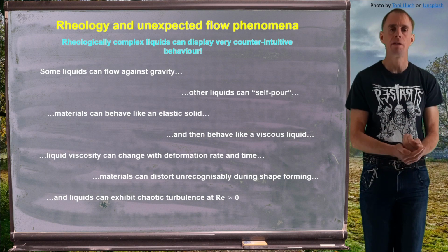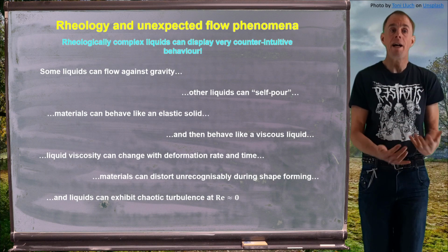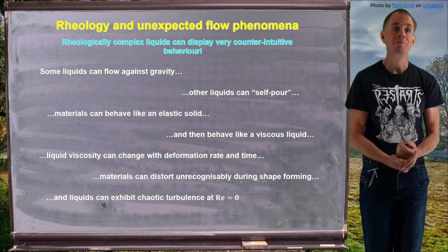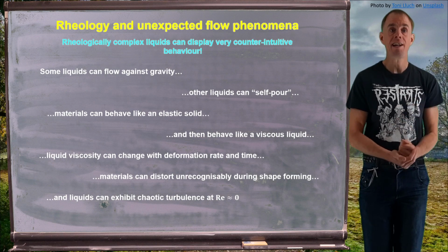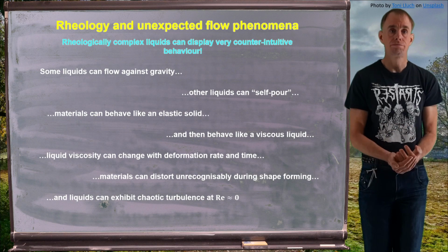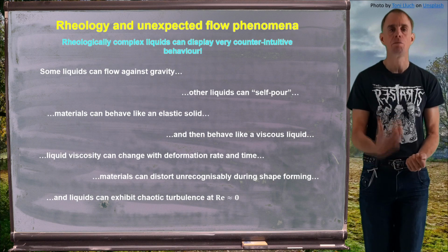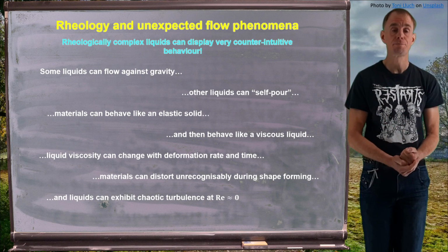Silly putty, for example. If you get silly putty and roll it up in a ball and throw that ball at a wall, it'll behave like a rubber ball. However, if you get that silly putty and leave it on a desk and come back an hour later, it will have formed a pool. And so you've got elastic behaviour at high deformation rate and viscous behaviour at low deformation rate.